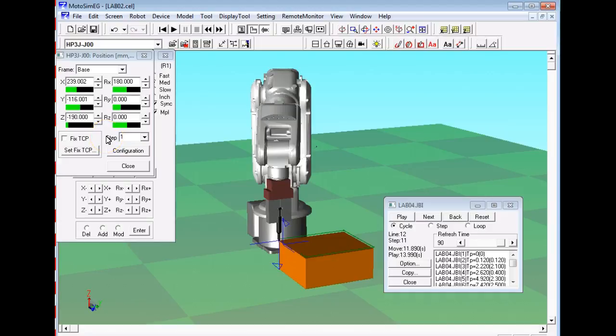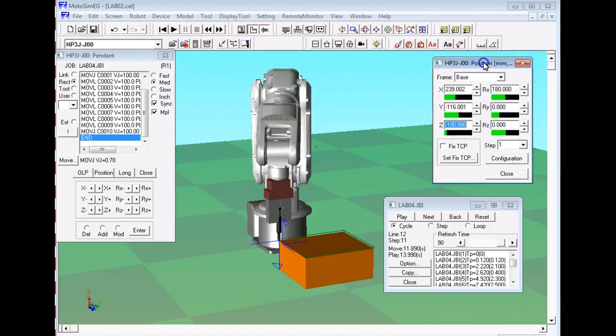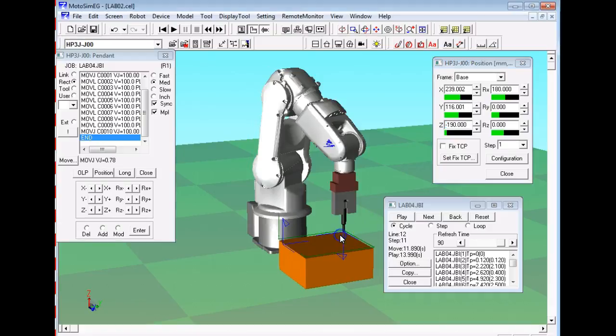Does that make sense? Yeah, we're not single stepping. What we're doing is we're moving in increments. So this is another way on this robot that we can jog it. Here we're jogging it Cartesian, but this is showing us the actual location inside our Cartesian system. So if I touch this point right here, this shows me the actual height of that move in a Cartesian system.